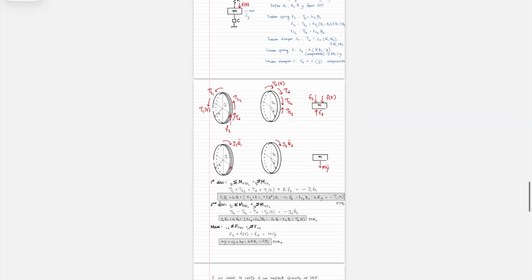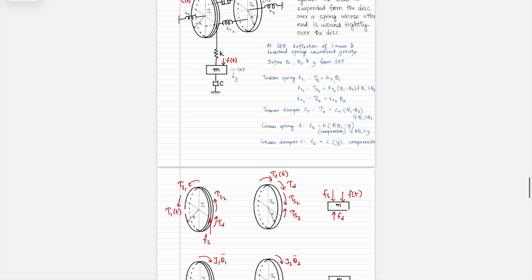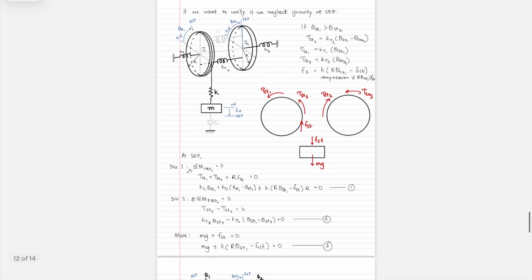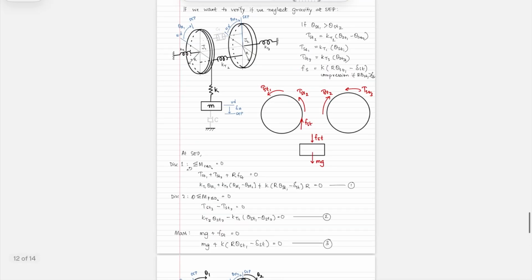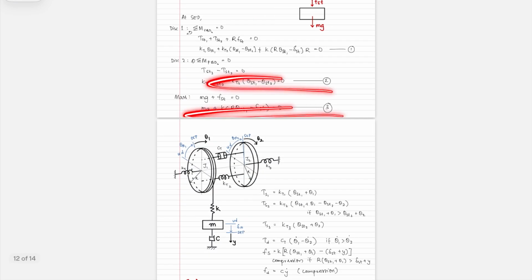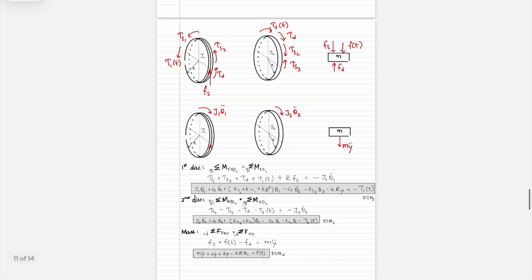So when you can see that the springs are acting against the gravitational force, then the static deflection will cancel out that gravitational force. So in general, if you're confident about that, you don't have to specifically verify using all of these relations, and you can just write down what we did in the first attempt. I hope that makes sense.